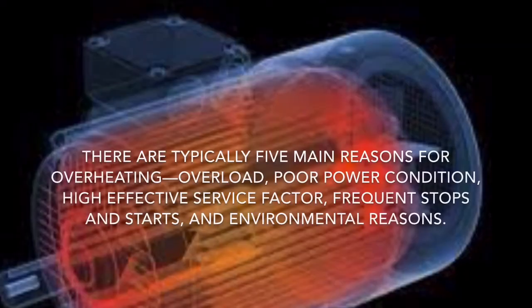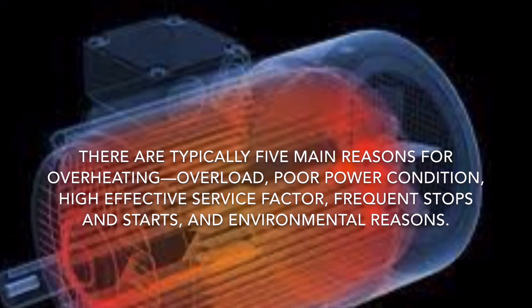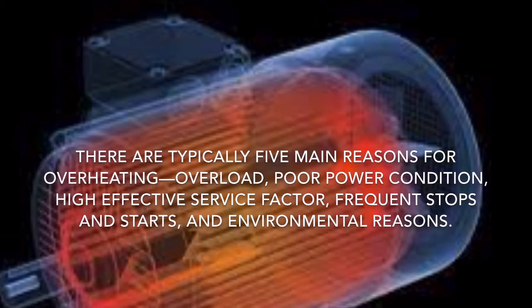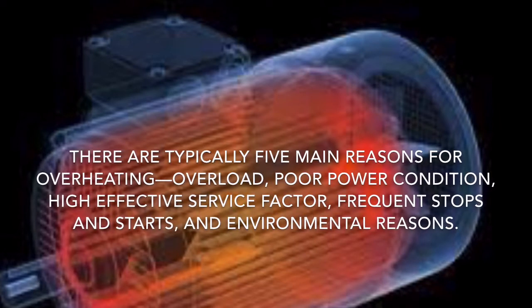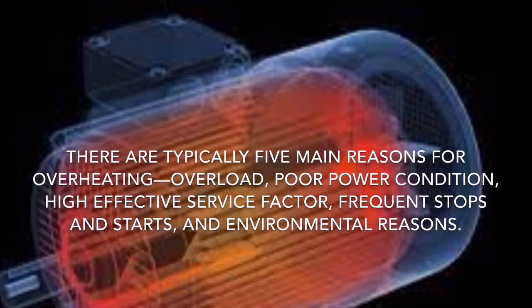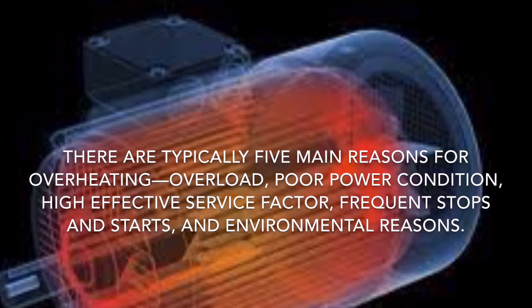Number 3. Overheating of a DC generator. There are typically 5 main reasons for overheating, which are overload, poor power condition, high effective service factor, frequent stops and starts, and environmental reasons.